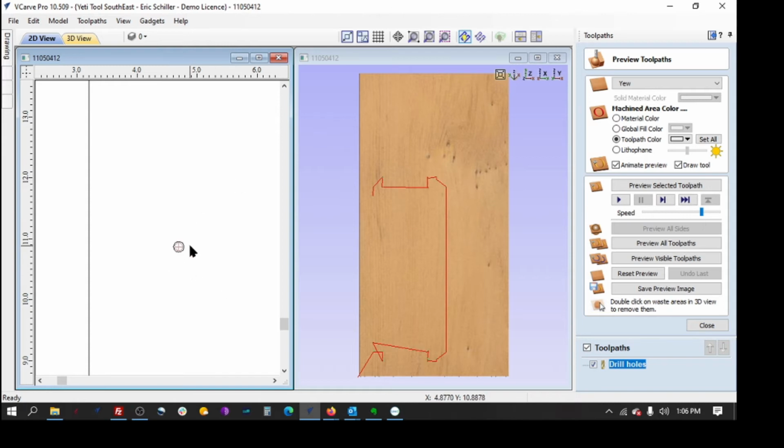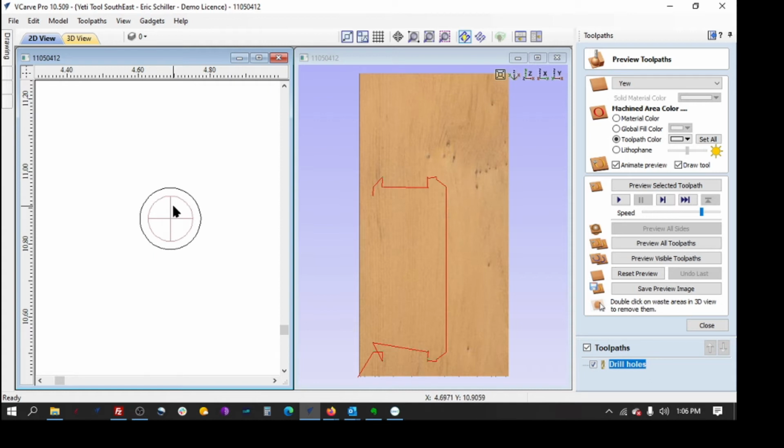So the way this is set up right now, I'm drilling. So I'm just doing a direct drop of the bit into that hole. I don't know if that hole needs to be machined the full 0.13 or if an 1/8 inch bit's going to be right, or if we just order a 0.13 cutter. All of that can vary.